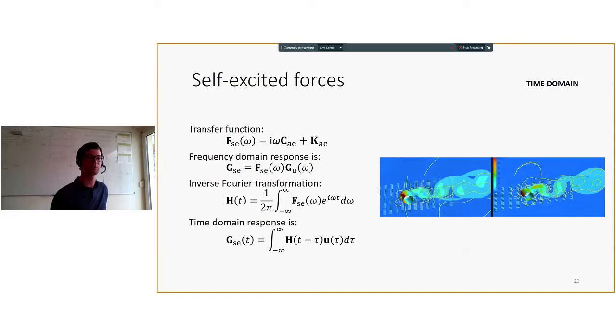This is, of course, very interesting research simulation. However, for some practical applications, I think at this point in time it is impossible to calculate it for so many objects on the bridge. Therefore, we describe this motion with frequency-dependent properties, and then with the right theory, we convert this into a Newmark scheme, and this is more practical for our application.